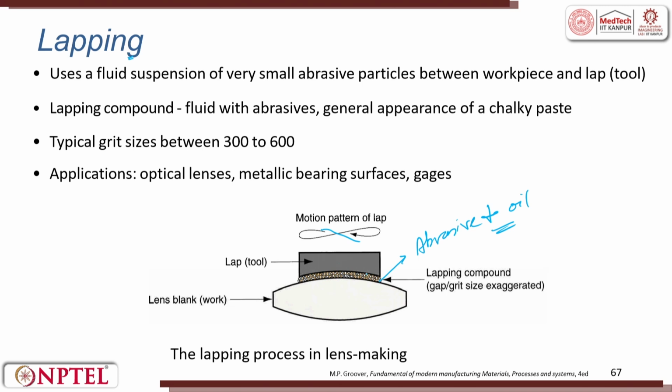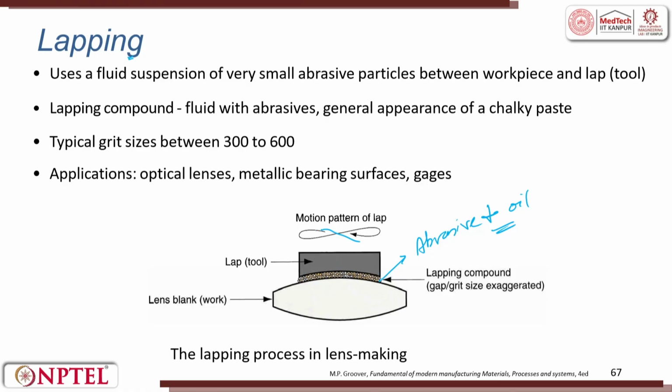It is almost like washing a vessel. So, you have a vessel which is a cylindrical milk vessel, or a pressure cooker which is cylindrical. Then you have your hand which is a lap. Then between the cooker or the vessel and the lap you have a brush. This brush has soap particles. So, that is the abrasive. You can move up and down, up and down, up and down and create, and depending upon the abrasive size, a very smooth surface finish can be generated.